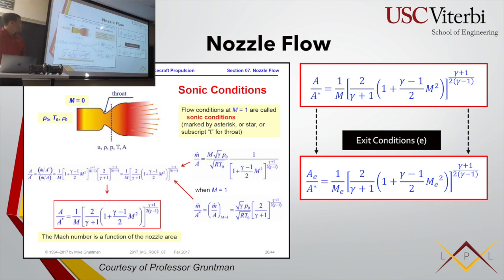So going into these, this is the one big equation here that ultimately talks about nozzle flow. So this is your area-Mach relation. Everyone knows this for rockets. When I have interviews, they'll ask me questions on this equation to see if I understand the concept, because the concept's important. So what this means is the Mach number is only a function of area.